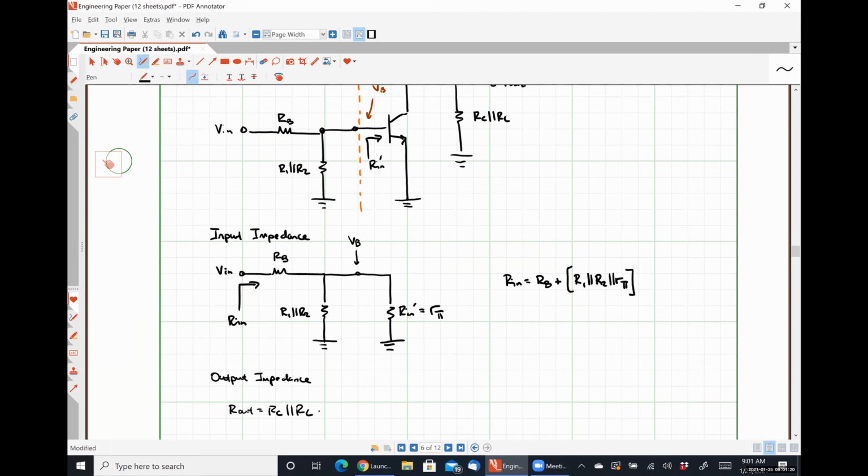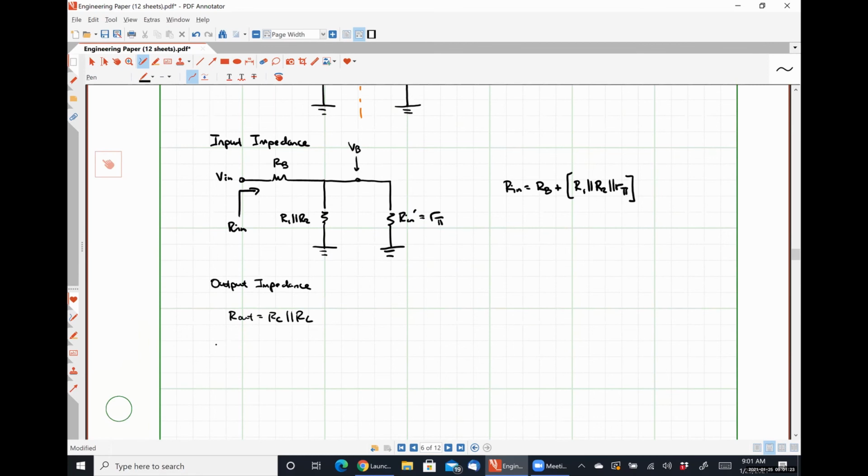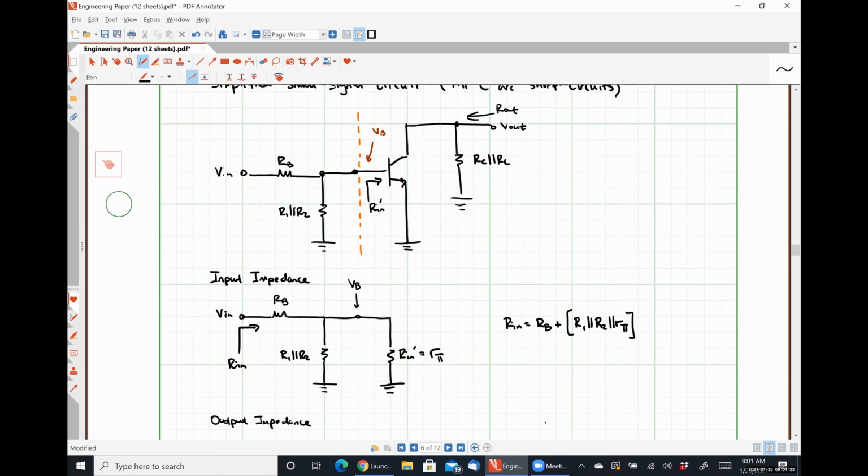Lastly, we need our voltage gain. So we're going to approach this in much the same way as we approached our last scheme where we just had a simple base resistance in series with our common emitter core, meaning that we can look at everything to the right as simply a common emitter amplifier that we know how it behaves, and then recognize that VB is just an attenuated version of our input voltage VN because it's being applied to a resistor network.